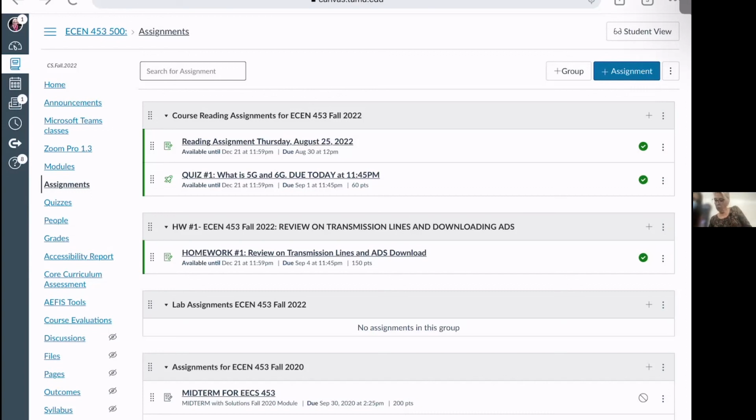If you put this to zero, what is happening? If this goes to infinity, this goes away, so I only have this left. You are going to have j Z0 tangent beta d over j R_L plus j X_L tangent beta d, and that goes away, and that's what you got.